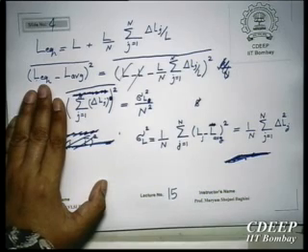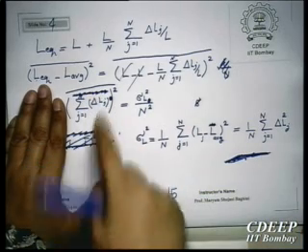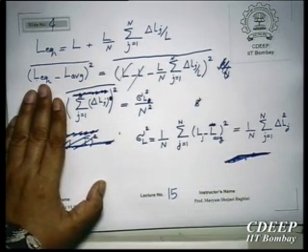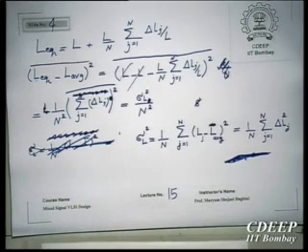No, but this is not summation. This is average of summation. So see, the whole point is, if I increase the number of transistors which are parallel, I will get a lower standard deviation.